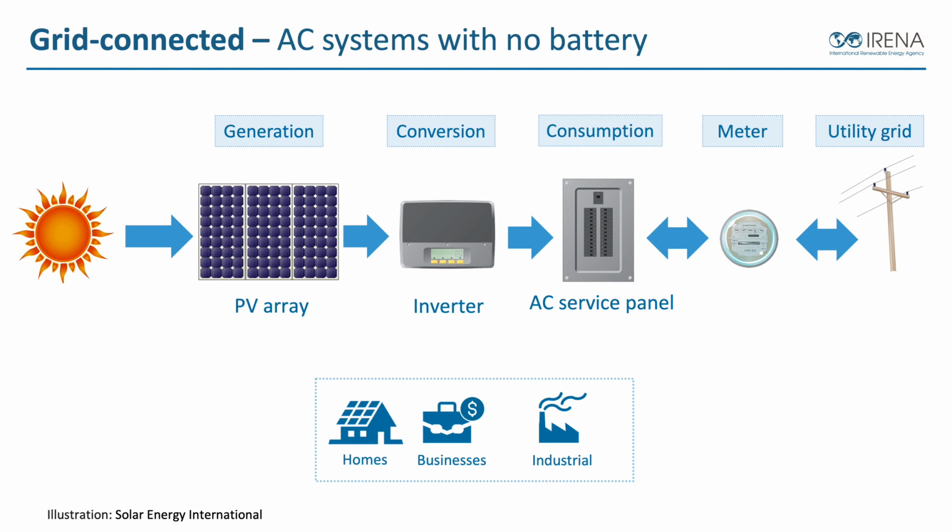That's because at any given time we could either be exporting or importing electricity, depending on the size of the solar, the size of our electrical consumption, and how sunny it is at that given moment. So when the sun shines, we have normal operation, we supply our panel, and we can either export or import at the same time to meet 100% of our AC electrical loads.